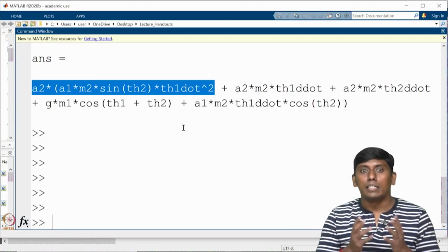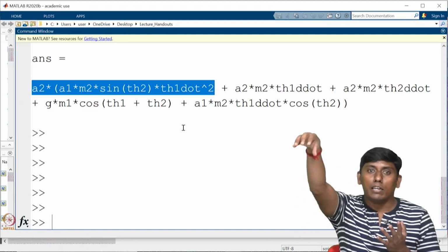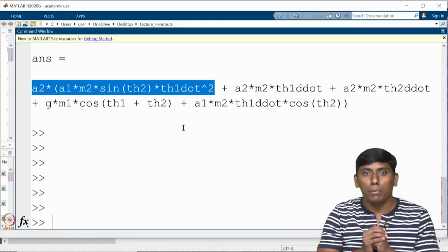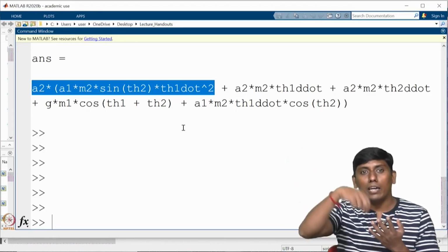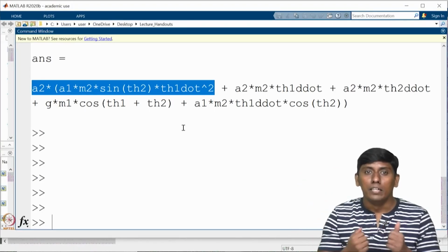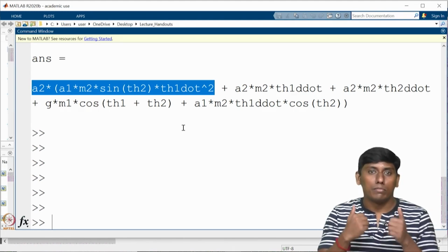For example, you are putting it on a mobile base, and your end effector is lifting something; if your support reaction is not enough, the vehicle will topple. So if you calculate the end effector to base forces, the shaking forces and moments, the support reaction comes directly. The support reaction is all the time positive.